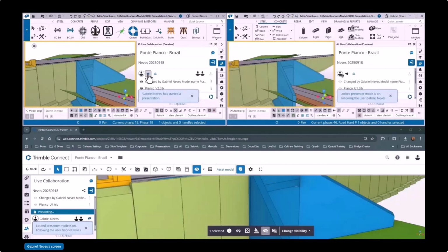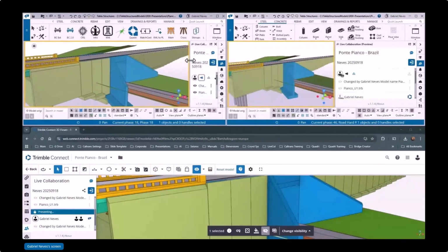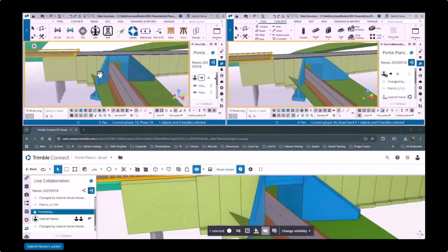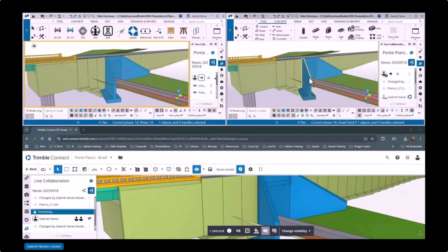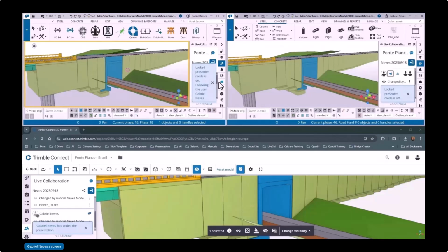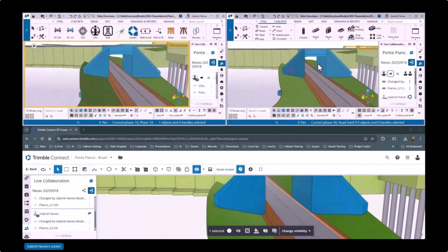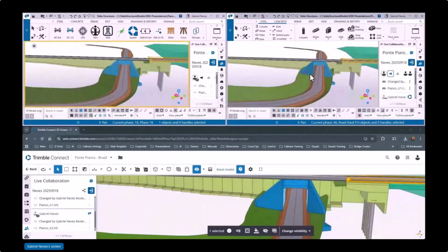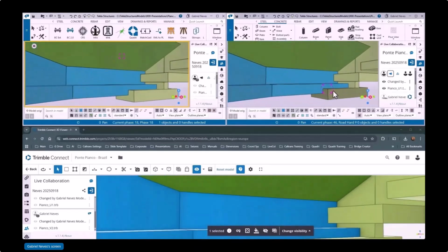And just remember to change all the view types to perspective, because then you can follow or force following one of the users, and see everyone now is following Tekla user number 1, right? That is giving instructions that, hey, delete that wall, right? And when he deletes, the other models update, and these models are there while you are inside the session. And funny enough, even after leaving the session, the one user could go and bring the session again, and the stuff is still there. Okay, stopped in time, but it's still there, right?